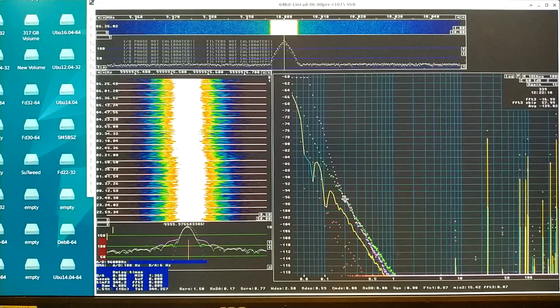But at 0.2 Hertz the result is reliable, and it is 100.5. And here both my reference oscillators are 4 decibels above the noise of the test object, which means that the oscillator I'm measuring is better than both oscillators at this offset. If it was equal, it would differ by 3 decibels from the yellow trace to the other two.